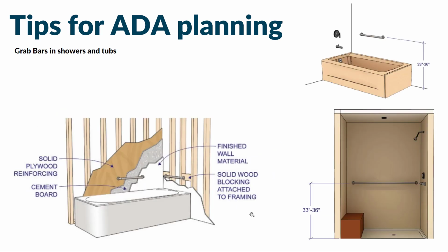And when we're thinking about grab bars in a bathroom, other than simply locating them at the right heights and distances that we can see on all these drawings, it's important to remember how buildings are built, how bathrooms are built. And so we've talked about before the wood frame construction that's typical in residential buildings, with all of those studs being 16 inches on center.